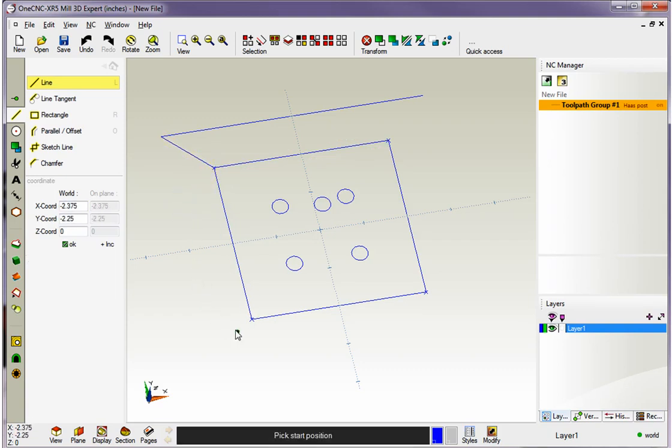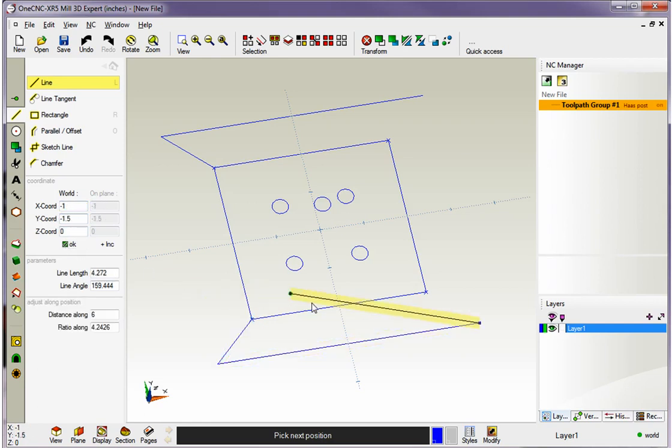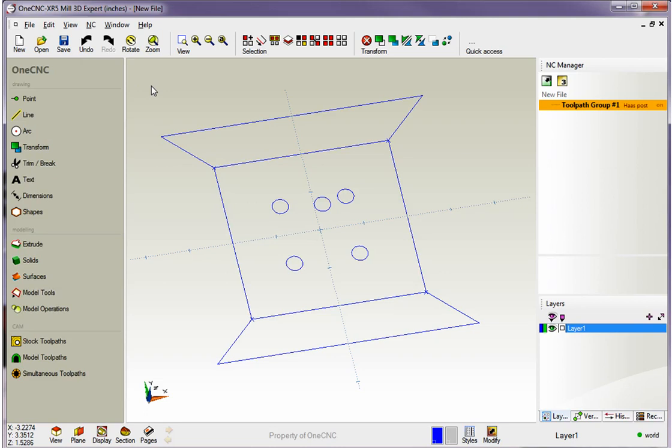Now for my new line, I'm going to come down here and left click that. Now I want to use coordinate input, so I just move over here and start to type in the information. We're going to go minus 3 for X, and minus 3 for Y. When we're done with that, we're going to click OK. Now we want to go all the way to X3. That looks good. I'll click OK. Now I'm simply going to move my cursor over here and left-hand mouse click. I'm finished with this line, so I'm going to right click, and now I simply want to join these two lines together, so I'm going to left click and left click, and then right click when we're finished. So there you go. You can combine your coordinate input with grid snapping, with entity snapping, or with datum snapping.